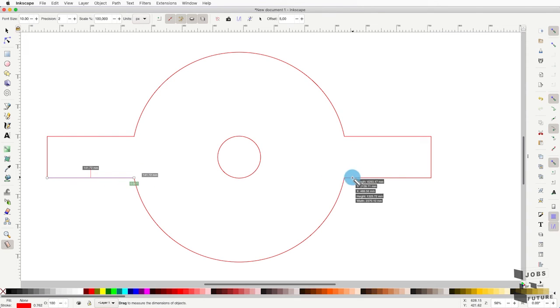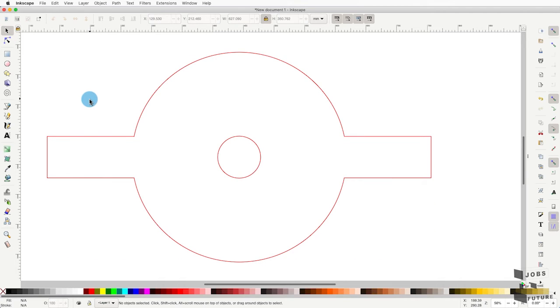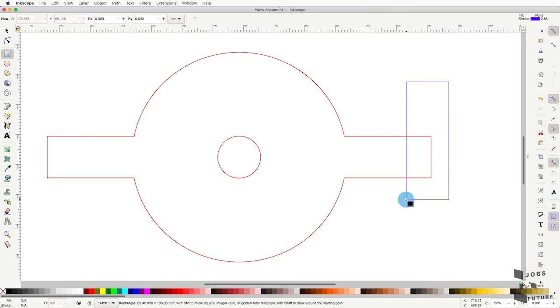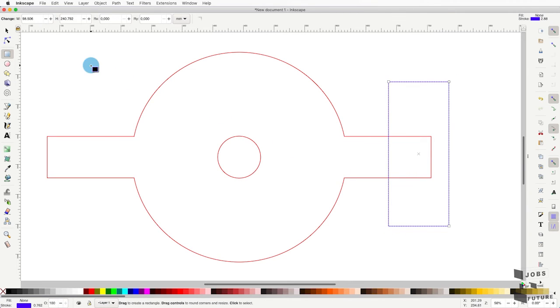So now I want to create some crease here, some lines that will help me to fold a little bit this long part in order to put it better on my recycle bin. My idea is to draw a rectangle, no matter the height, but I can choose the other dimensions. So I can switch off the locker, and let's say that it should be 80 millimeters.